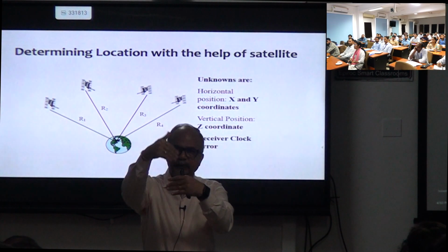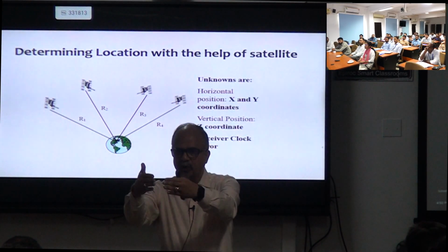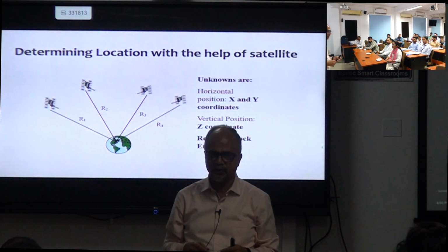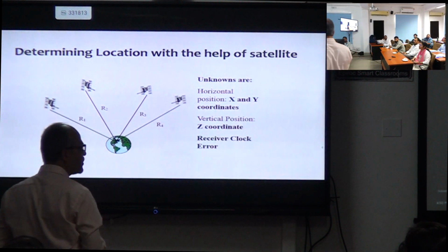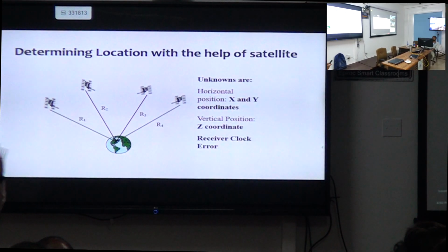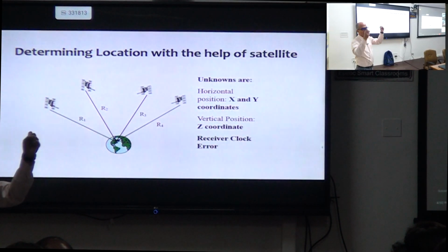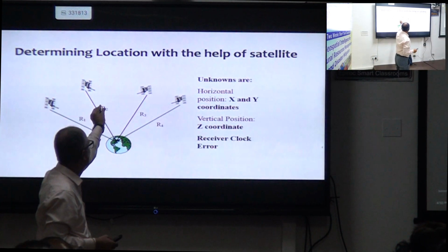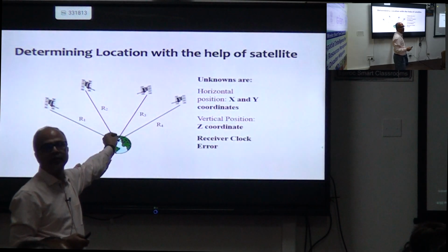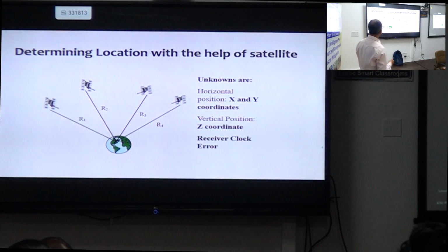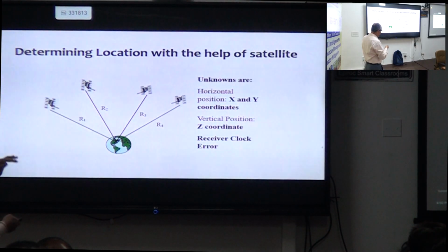But here, though the difference is the same, 3 meter, the angle is there, and here also we have the difference of angle. So similarly, this is one point why I am mentioning, because when we take GPS reading, which satellite we are capturing is extremely important. If suppose 4 satellites are very close, then we will not be able to get a very correct reading. Okay.